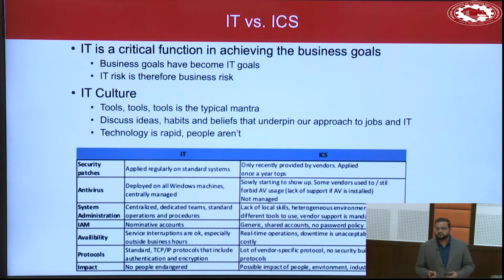One of the reasons is, as we talked about yesterday, SCADA system. Yeah, so what it does, it captures all the data and then passes this data to its central system, which runs the algorithm. So for example, if we are talking about power system or smart grid, we have power algorithms that we run just to see power flow, whether everything looks fine, devices are working properly, and the level of voltage and current that should be there is working perfectly or not.